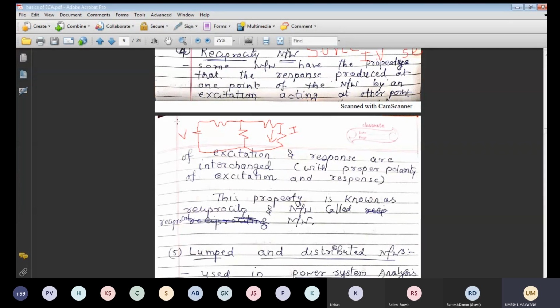So when you connect the voltage to this circuit and find the current, because these two are connected in series, this one with the parallel, it is a series-parallel combination, you can find the total current in this branch I. And you want to find the current I1. Using the current division theory, you can find the value of I1. So this is case 1, when we connect the voltage in this position.